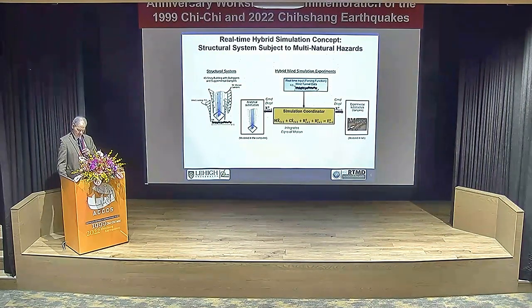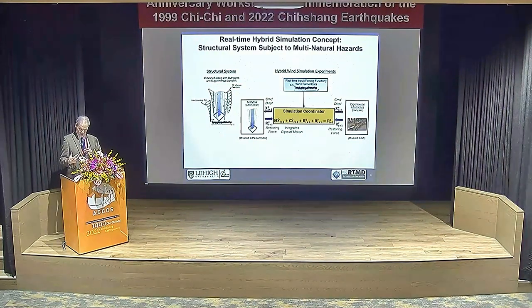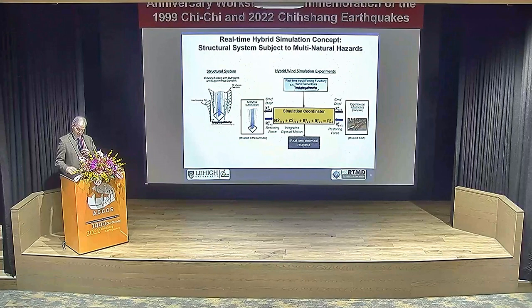But you issue those commands, and then what you ask in return is restoring forces. And this has to be within the time step that you assign. If it's real time, that could be a very short amount of time. But if you're able to do that, you go to the next time step. If you can't do that, like Professor Nakashima, you want to hide because chaos could develop and things could blow up on you. But if you're able to do that in real time, that's a real-time response.